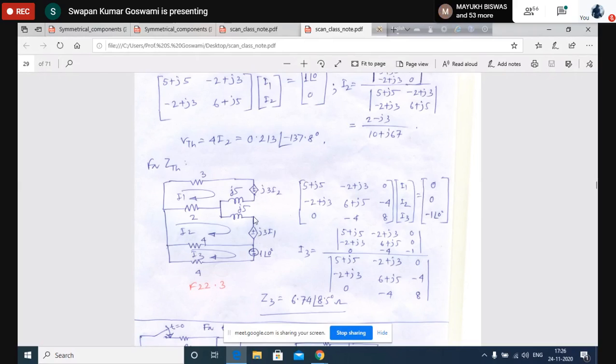Okay, these sources are here, but you must arrange the current to flow through these inductors. Otherwise, these EMFs will not be induced. So an independent source is required. So here, where we measure the Thevenin impedance, you connect a voltage source of say 1 volt at an angle of 0.